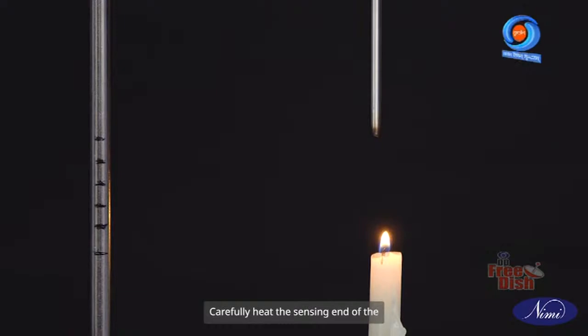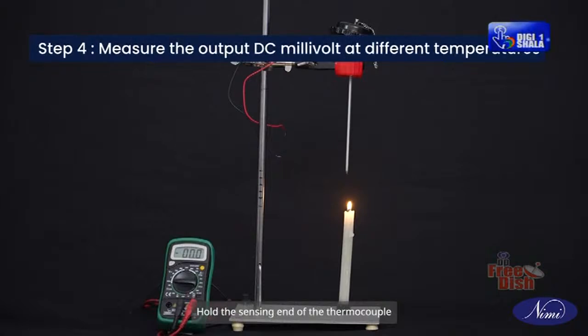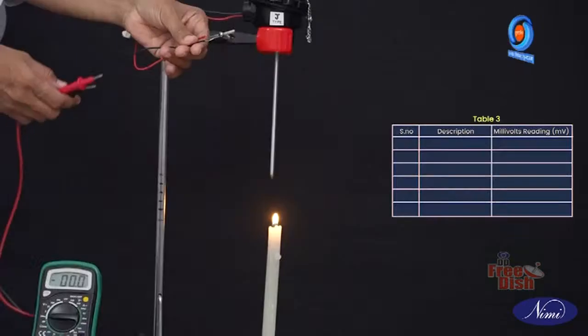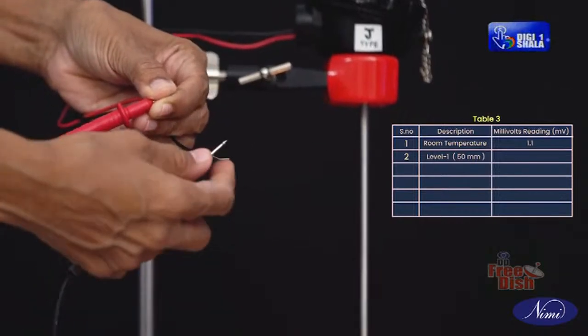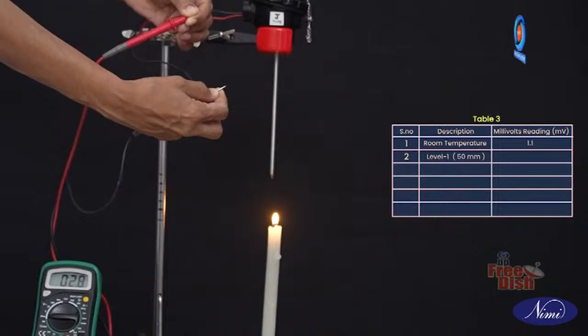Carefully heat the sensing end of the thermocouple using the flame from the candle. Hold the sensing end of the thermocouple near the flame for 5 to 10 seconds. Now observe the DC millivolt reading for the first height, 50 mm, and record the value. This initial reading serves as a reference point for comparison.